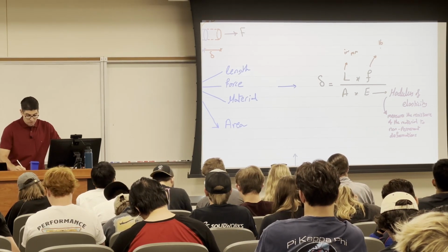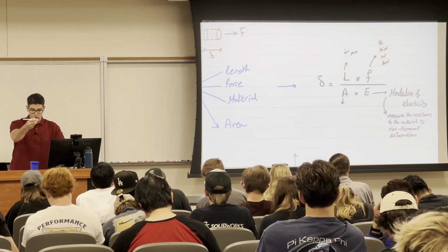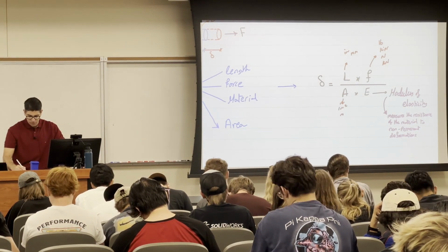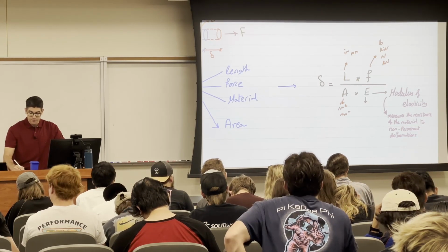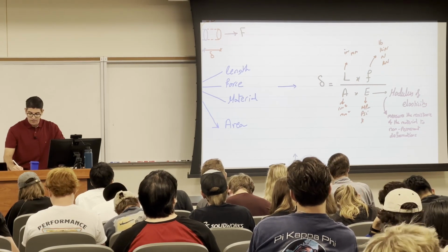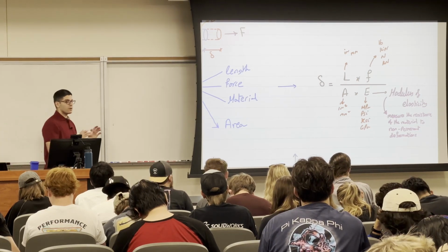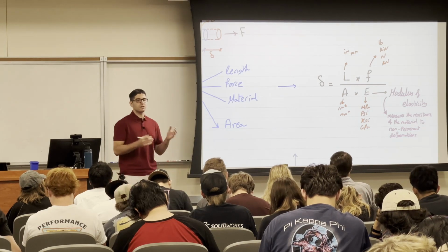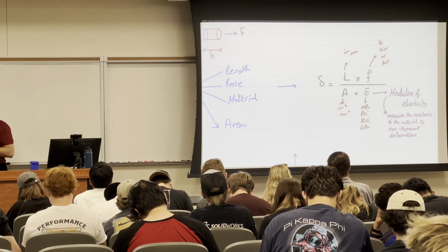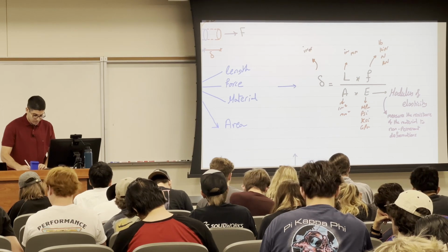Force, pounds, kips, newtons, kilonewtons. The area, you need to follow what the length was in units so that you can cancel them together, either inch square or millimeter square. And E is in a unit of stress, which is MPa, PSI, KSI, for example, or gigapascal. But you want to have your units in that equation and all the equations throughout this class consistent so that you're able to cancel the force with the forces or the length with the lengths. And the delta eventually will be in a unit of inches or millimeter.